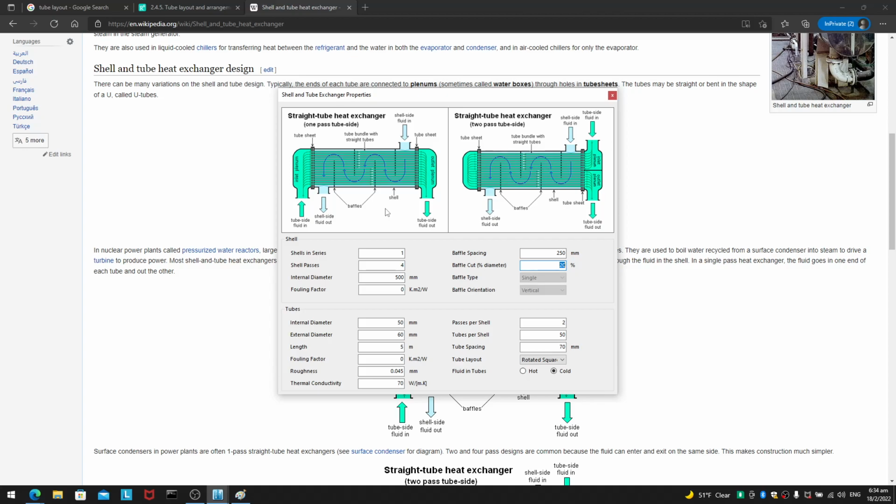And in fact, turbulent flow will tend to provide better heat exchange, because it minimizes the boundary layer. But having turbulent flow may also increase the pressure drop. So there is some sort of trade-off here if you want to use turbulent flow or you want to force the fluid across like that.